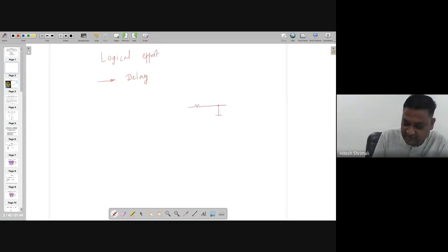Let's assume that there is a circuit which is like this. I'm drawing R and C because we know that most of the time whenever any MOS transistor is there, there will be resistance and capacitance. We are not adding an inductor, with the assumption that there are no inductive effects. But at very high frequency, it might happen that you will have an inductor. But for the time being, let's assume that RC are there and you are giving V in. You know that the input is like this, but the output is actually delayed like this.